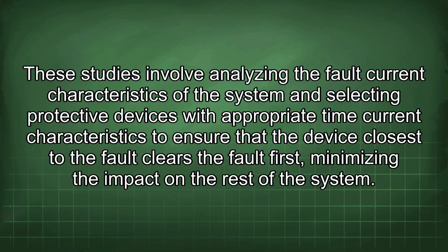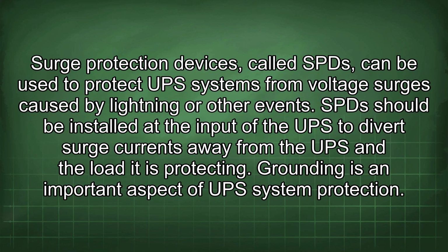Surge protection devices, called SPD, can be used to protect UPS systems from voltage surges caused by lightning or other events. SPD should be installed at the input of the UPS to divert surge currents away from the UPS and the load it is protecting.